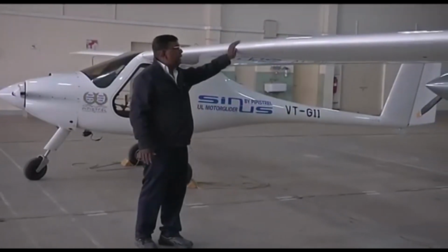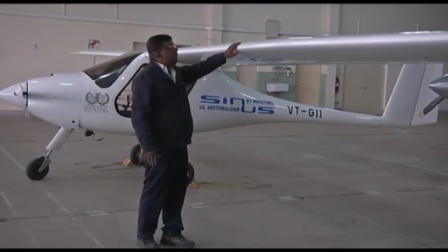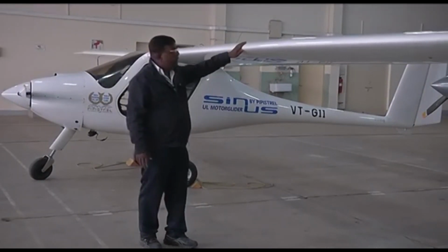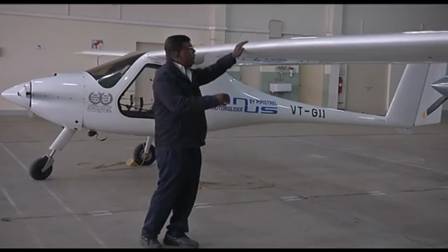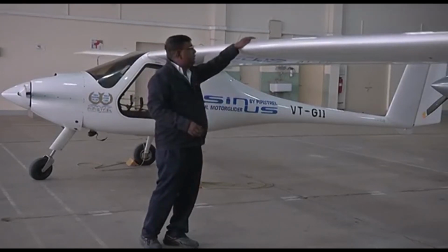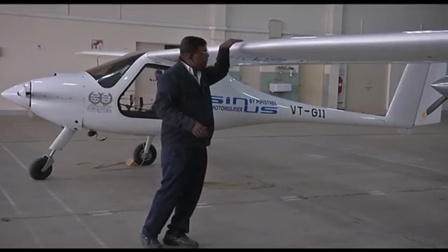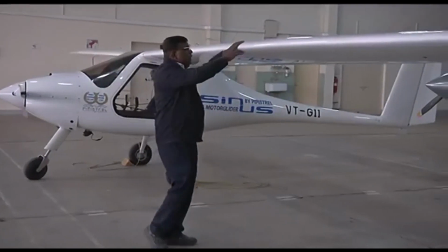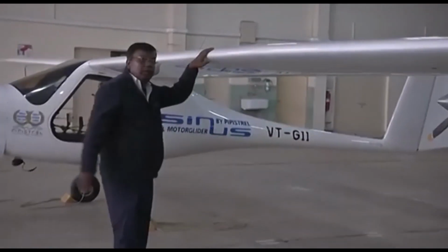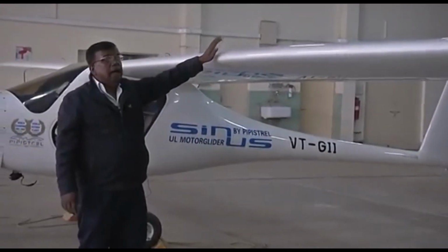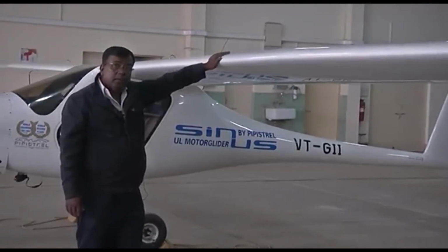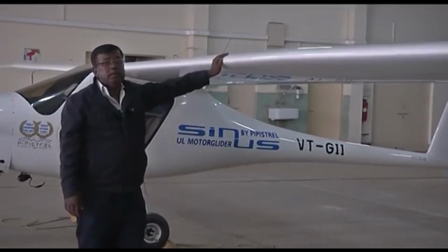The moment there is an additional angle of attack, there will be additional drag because it comes through the drag polar. And the additional drag, which will be acting towards the tail, in that direction, will give a nose-up moment about center of gravity. So high wing is not preferred as far as longitudinal stability is concerned.